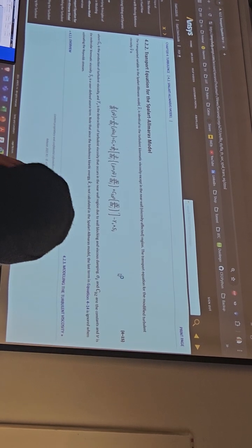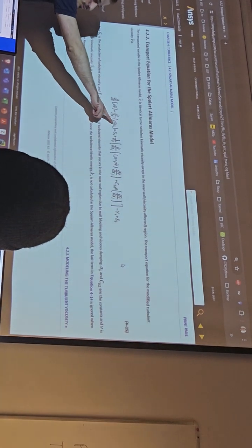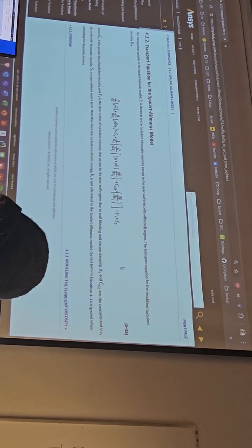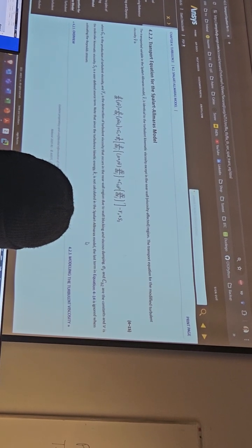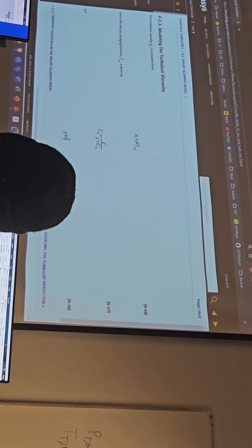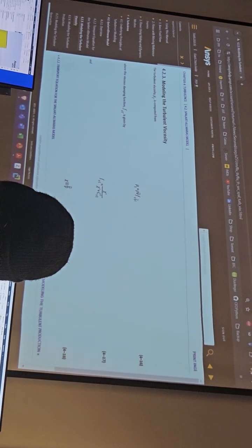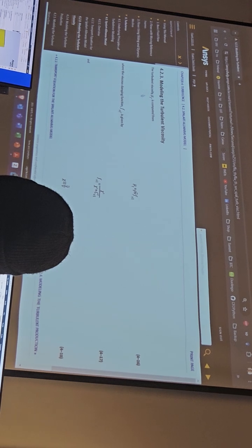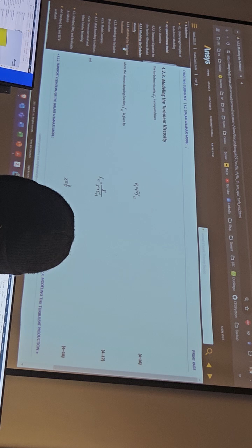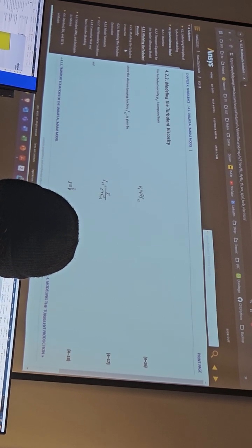And then here you also have the transport equation. The solver will be solving this equation where the variable that you are solving for is this nu, that is the eddy viscosity, or something related to the eddy viscosity. You can also find more information about this variable that is solved, how it's related to the turbulent viscosity. Actually, that is the one that we need, and also some other information about the source terms if you are interested.